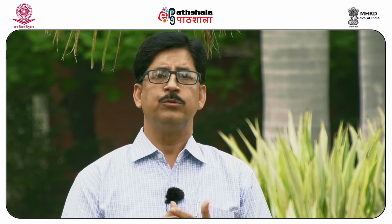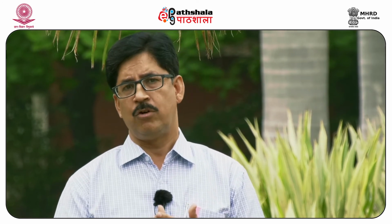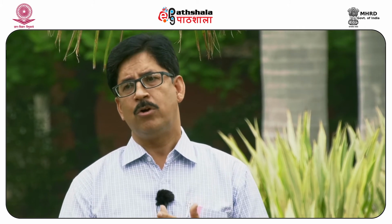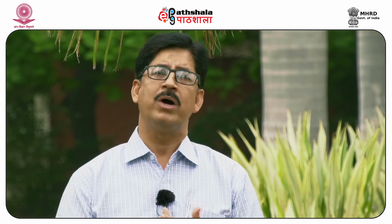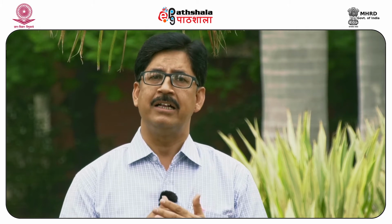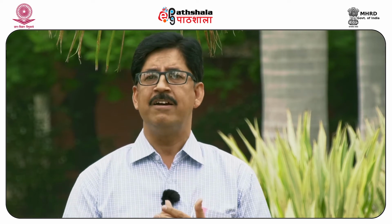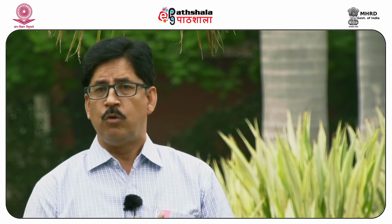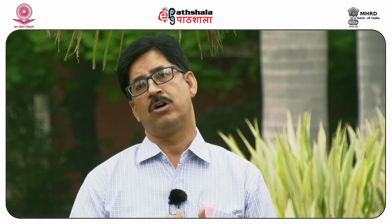There again we have to take this loose and weak material along the fault zone and fill it with concrete. But the most important thing is that we should avoid faults, and if we cannot avoid a fault, then the fault should come at 90 degrees to your structures, so that you have a minimum of its effect on your structures. Now, faults also result in the repetition and omission of rocks.